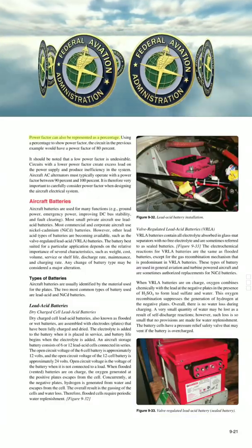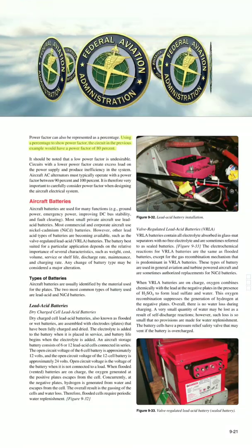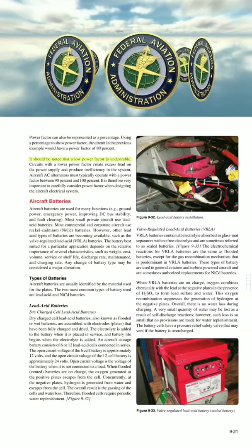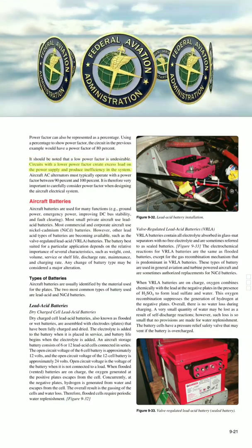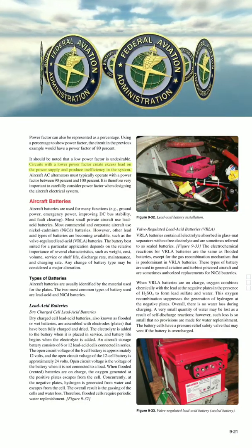Power factor can also be represented as a percentage. Using a percentage to show power factor, the circuit in the previous example would have a power factor of 80%. It should be noted that a low power factor is undesirable. Circuits with a lower power factor create excess load on the power supply and produce inefficiency in the system.